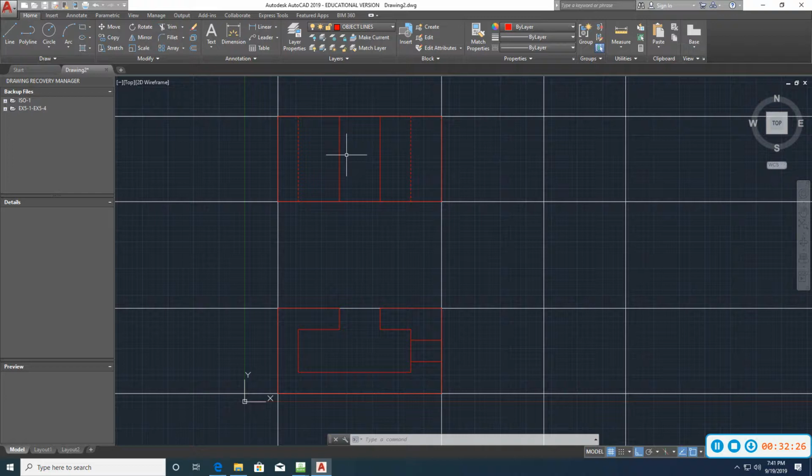How about these 2 lines right here? They should stay as a solid line, right? But we have this notch cut out here. Does that notch go all the way through? It doesn't go all the way through, does it? How far does that notch on the right side go into the block? 20, right? You all see that notch? It goes in 20 from the corner. So what we're going to do is we're going to offset 20.